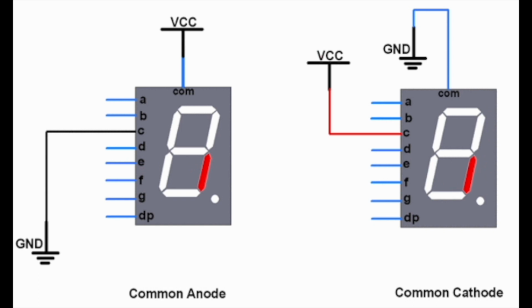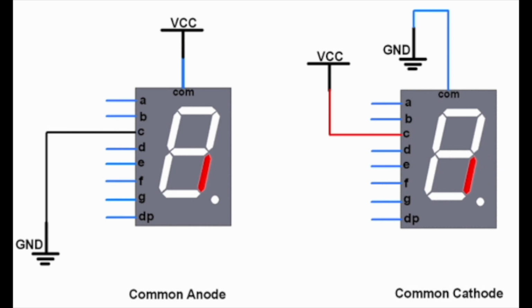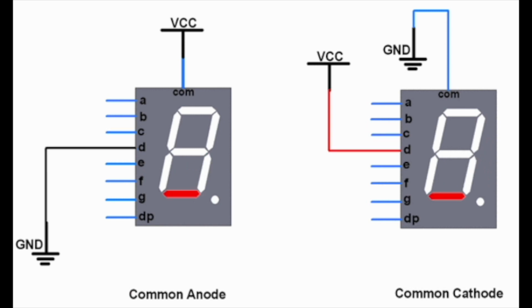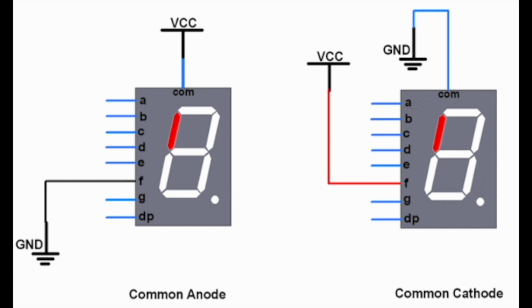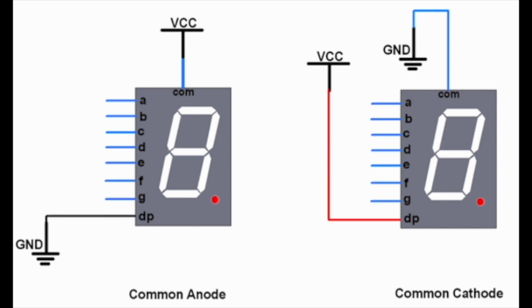So here the complements are used for driving the common cathode arrangement when we are referring to the voltages from the controller. For displaying the segments, we will have to drive the appropriate voltage on the segment level. Segment C of a common anode will be illuminated when the C port line is grounded. Here in the common cathode setup, the port line needs to be connected to a higher voltage, which is VCC or a digital one. Likewise, individually the segments need to be appropriately driven.